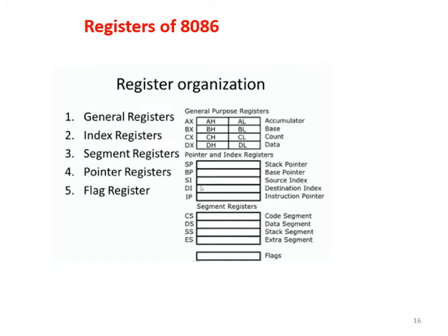And you can see here your AX register is of size 16-bit. But for our ease of calculations and computations, you can even divide that 16-bit register into two parts, AH and AL. The lower part of the 16-bit is defined by the name AL, and the higher part of AX is AH. Why do you want to divide it?